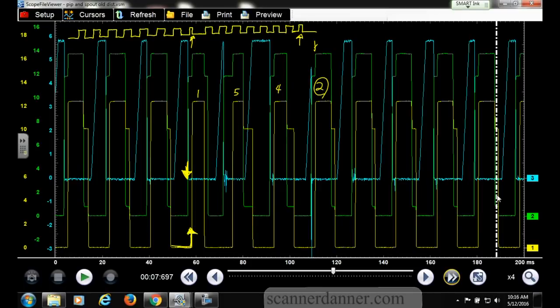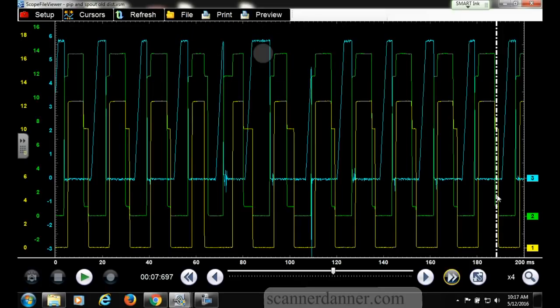So 1542, that's pretty cool. And I agree with what you said, Kendall, that it seems like the number 1 cylinder is initiating this whole sequence of events. Once we see the number 1 skinny pulse, it's the next one over that really gets messed up by it. We see this guy, and then we see that really long clipped area afterward. And then it starts to get better after that, doesn't it? The rest of these seem more consistent. Let's see if we see that same pattern.